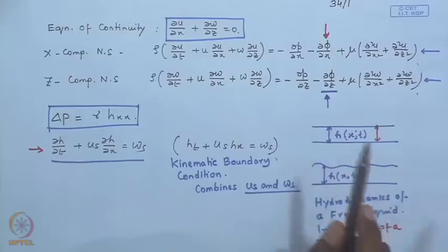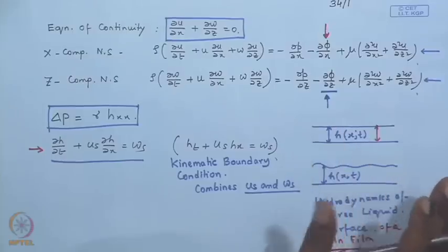It is the Navier-Stokes equation which incorporates the effective interface potential, that is, it is valid for any system where there is an additional interfacial interaction. Now, the expression of phi can have terms which represent only the van der Waals interaction, or additional terms that take care of additional interactions, let us say acid base, polar or steric interactions.